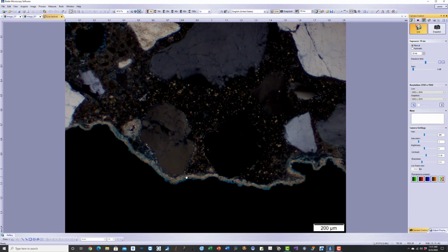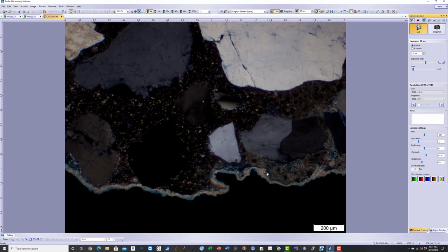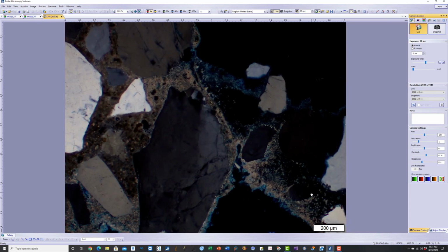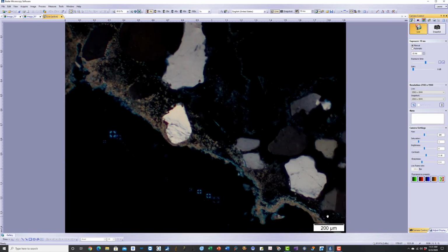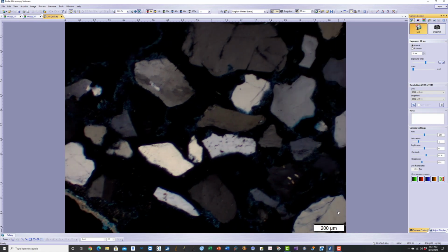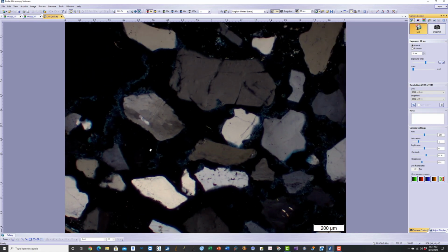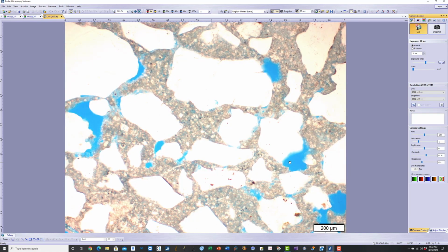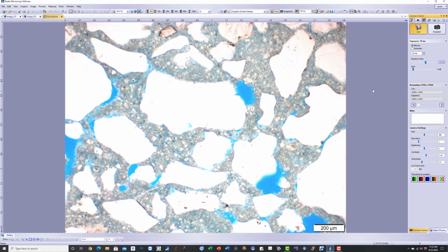Here you can see the secondary calcium carbonate ring formed at the edge of the dense paste of the jointing mortar. This area is very dark because of the leaching, but the calcium hydroxide component and the calcium silicate hydrate component of the cement hydration has been leached out. So it created more or less porous patches of the paste.